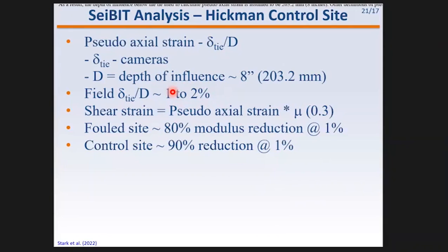So when we run a surface wave measurement, these surface waves are going through the ballast and the track system, but it's a very small excitation, very small. So we are measuring a very small strain shear wave velocity and shear modulus, okay? Of course, when a train goes past, we are not in the very small strain category. You see the track moving quite a bit. And so we have to use a modulus reduction relationship to convert our shear wave velocities to a larger shear strain.